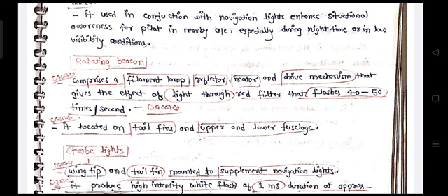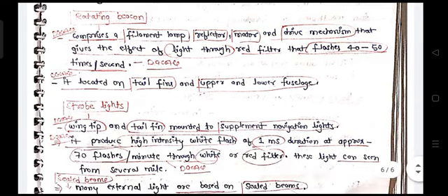So navigation light will be on the left, the right and the back. Along with that the strobe lights will also be on. Then there is the rotating beacon that we have already read. It has a driving mechanism in which the filament bulb will be reflected through a reflector and the motor will rotate that bulb in all directions. Generally the question is how many flashes take place in a rotating beacon. It is 40 to 50 times per second. Remember that, not per minute, per second.